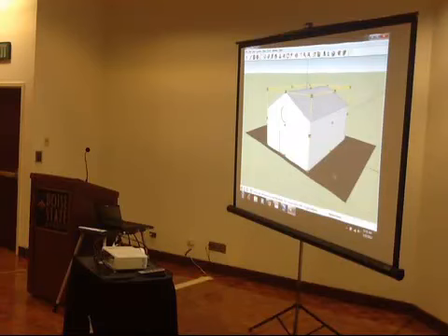Bronco Stadium. If you click on Bronco Stadium, it'll come up and say unable to view the file, because it's not able to preview it. But our magic little Open In icon up in the right-hand corner should, once you've got it installed, show SiteSpace as an option. There it is. This is a file that was created in SketchUp, saved as a KMZ file, and we're now able to open it from within this application and move around.